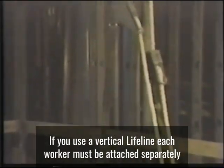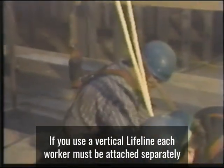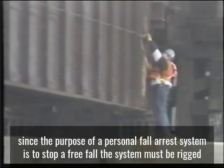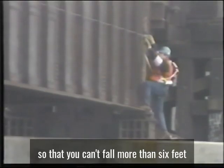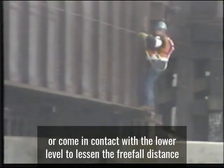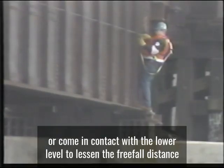If you use a vertical lifeline, each worker must be attached separately. Since the purpose of a personal fall arrest system is to stop a free fall, the system must be rigged so that you can't fall more than 6 feet or come in contact with the lower level.